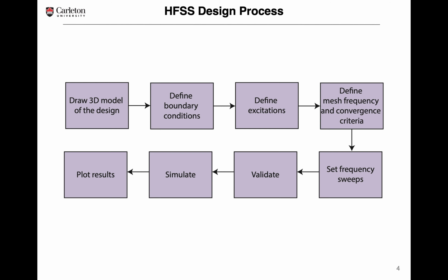All right, so the HFSS design process has a number of steps, and while you're starting to use the software, it's a good idea to keep those in mind, just to make sure that you're doing everything right. So the first step is to design the structure. It's going to be a 3D model of your design, and for that you just use HFSS CAD-like drawings, so you can draw rectangles, circles, etc.